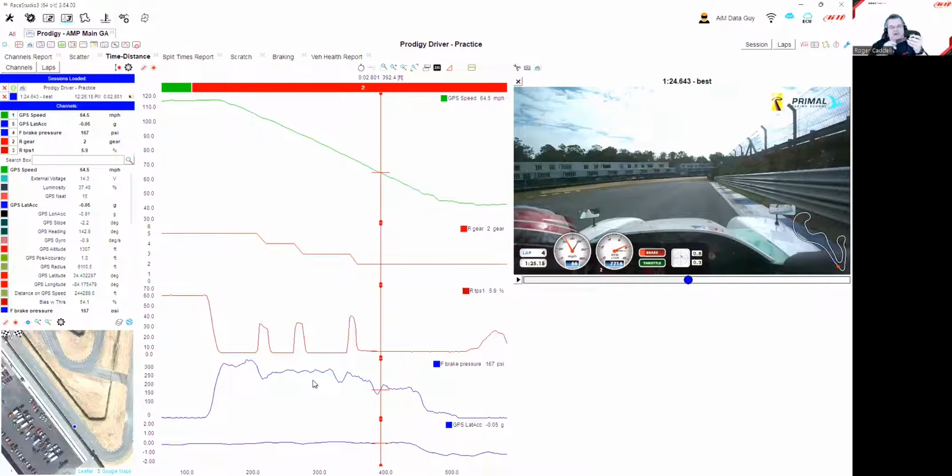If you release the brake partway through the braking zone, the car will release some front end weight, and then you hit it again, and you begin this process where all four tires are getting changing loads as we head into the corner. In straight line braking, if you're at the limit, this is going to be a problem. If you're just below the limit, it's probably hidden from you a little bit. It's not the end of the world.